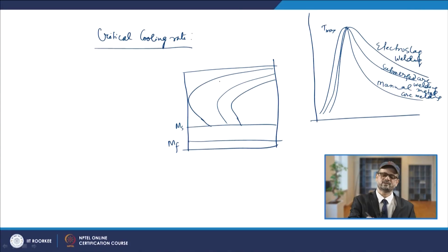So austenite will be transformed to pearlite, and based on where it ends, you will have coarse pearlite formation or fine pearlite formation, and accordingly you can predict that there will be either bainitic transformation, or, as we have studied about other types of transformations, the formation of bainite will be there if it is past the nose of the C curve and then you are holding here.